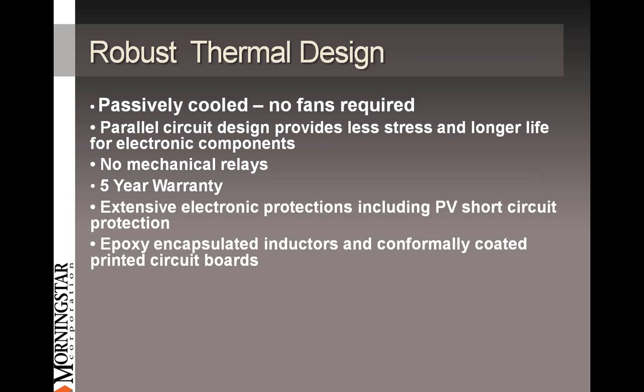But with a MOSFET board in there, we're able to shut it off in the event that it gets overcurrented too quickly. So that's another advantage. And lastly, we use both the combination of our epoxy encapsulation that you'll often see in the sun savers and a conformally coated circuit board, which is used on the larger controllers.